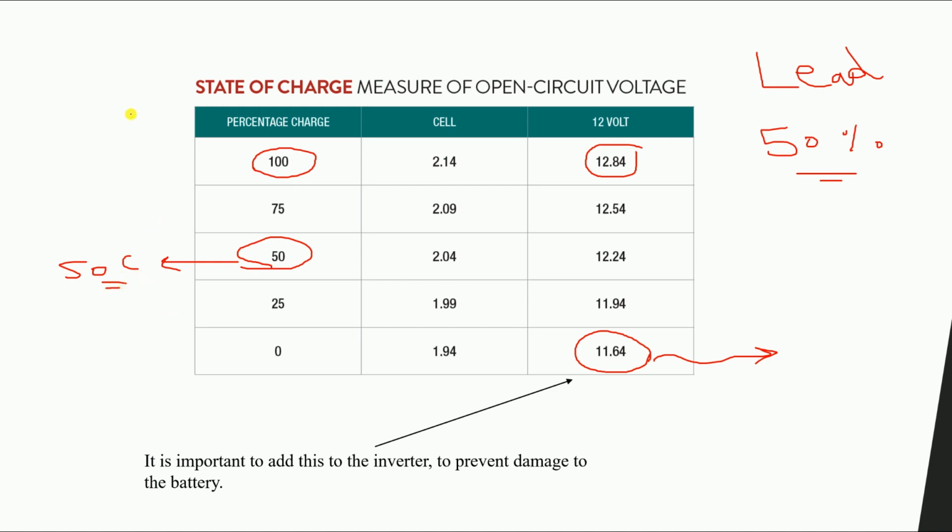For example, inside the inverter, if the battery reaches a state of charge of 50% and the grid is available, then you can disconnect the battery. If the grid is not available and my loads are critical and more important than the battery, then you can discharge above 50%. This is found inside the settings of the inverter itself.